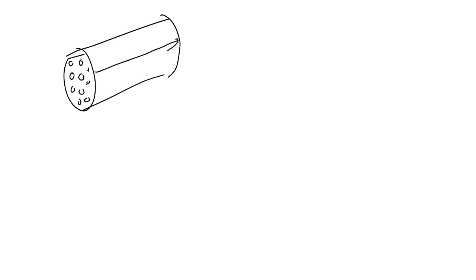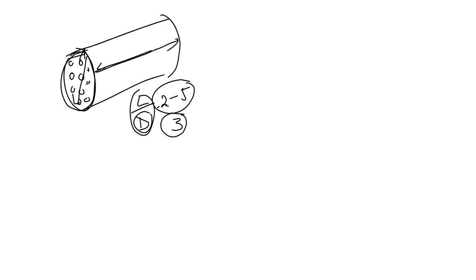Typically, the length over the diameter ratio of a reactor, the figures quoted between 2 and 5 are realistic. 3 is popular, right? And this length over diameter refers to the whole bundle diameter of your tubes. So it's not just one tube diameter.